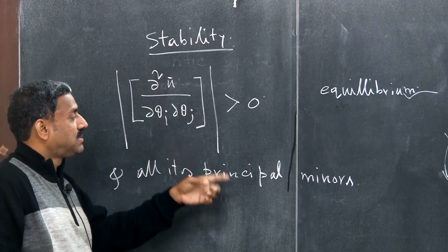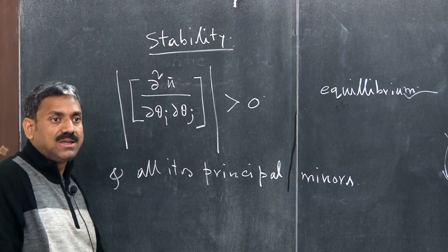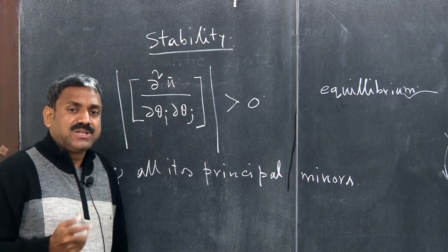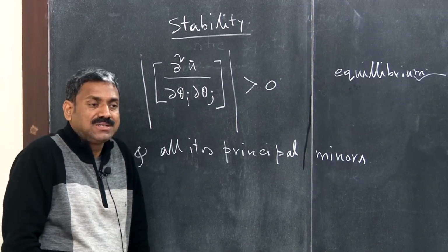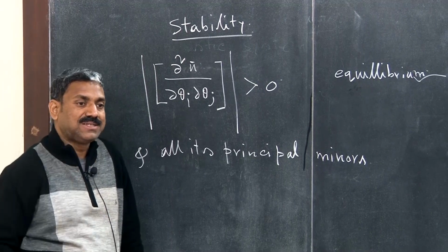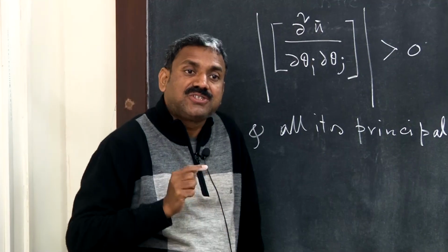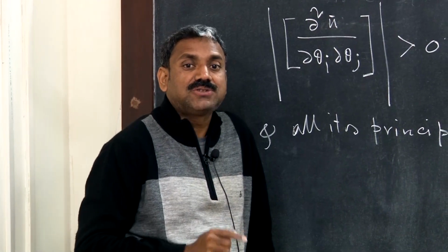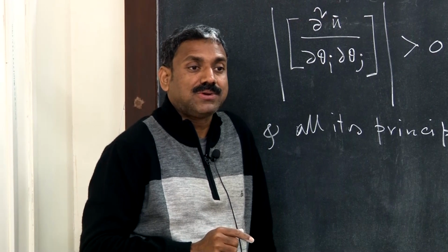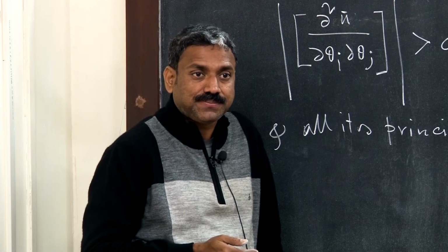If the determinant and principal minors are 0, then it is neutral equilibrium. Clear? Not necessarily do we have to follow an energy approach to analyze stability, but this is most intuitive, and the first class of stability started with this energy concept. It is also easy to deal with the potential energy functional.